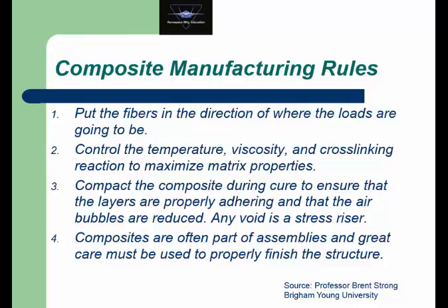If we have a high viscosity, the liquid doesn't want to flow into all the discontinuities on the surface of the fiber, so that we don't get a very good mechanical bond, then we lose strength of the overall composite structure.